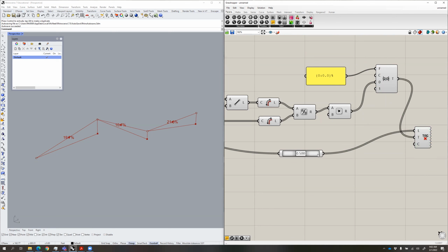And then what we'll do is also, this component here, this point here, you can see it's kind of overlapping with the numbers. So you can just turn that off. So just click on that, preview off. And then, like I said before, a little trick you can do: this number is just sitting on top of that line. If you wanted to offset it a little bit, you can either put some spaces to the left of it or some spaces to the right of it. It doesn't really matter. Let's just do that. You can see it begins to move it over a little bit. So you can make it sit next to the line a little bit nicer, like so. Made it one more space maybe.